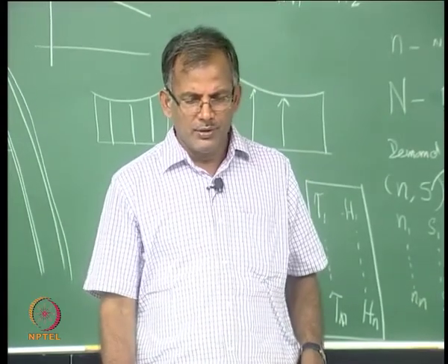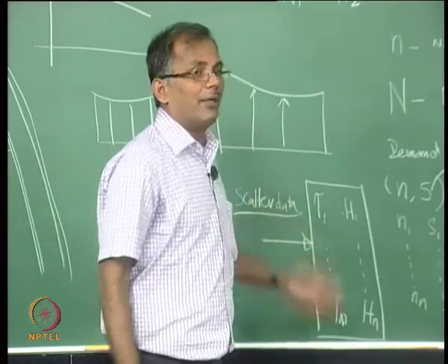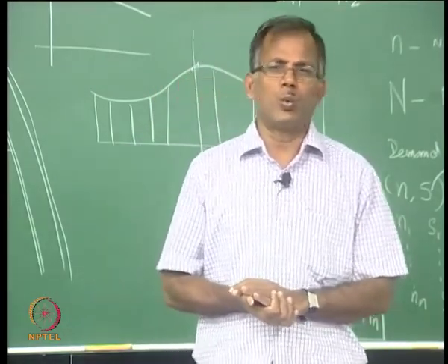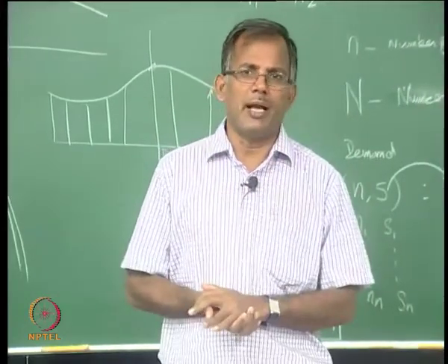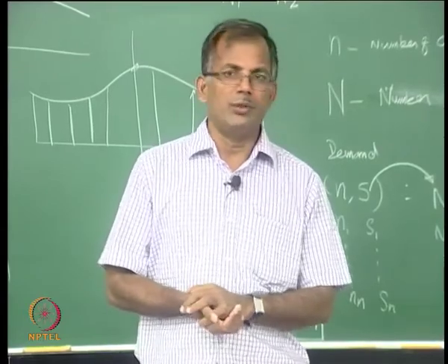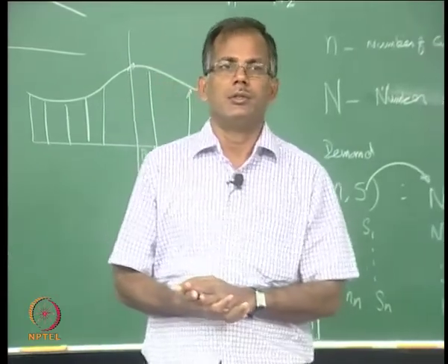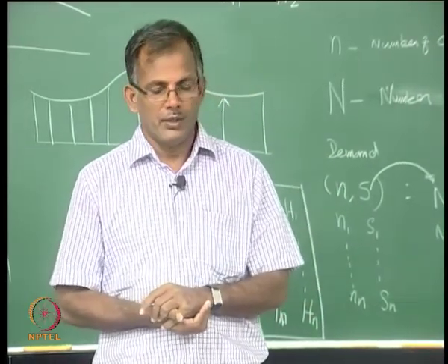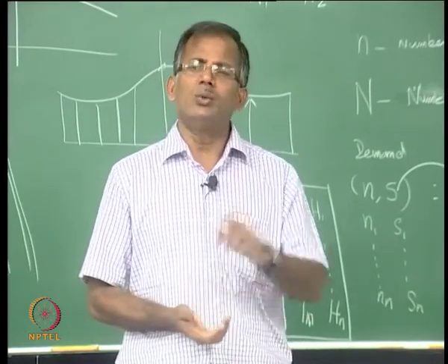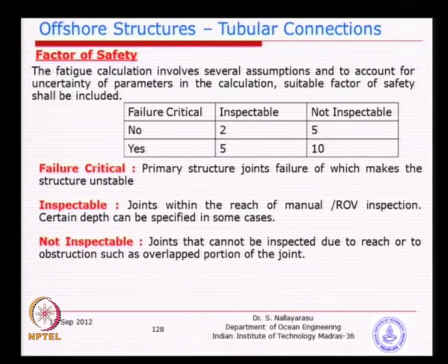But in recent times, studies indicate that the scatter data, basically the amount of information available to the designers, is quite limited, because nobody wants to spend time and money measuring waves at a particular site. They normally use mathematical simulation. But as you know very well, mathematical simulation has serious limitations, and that is why you have to apply higher factors of safety.